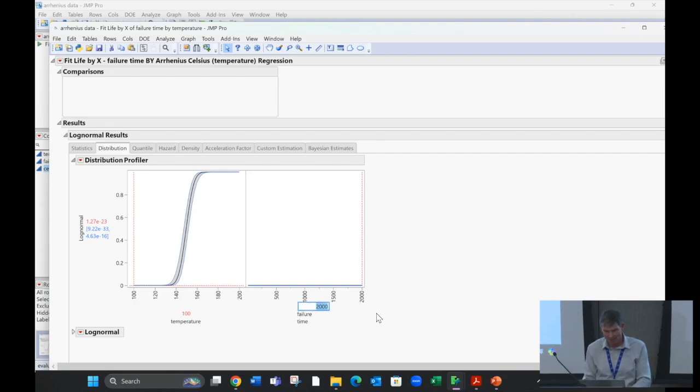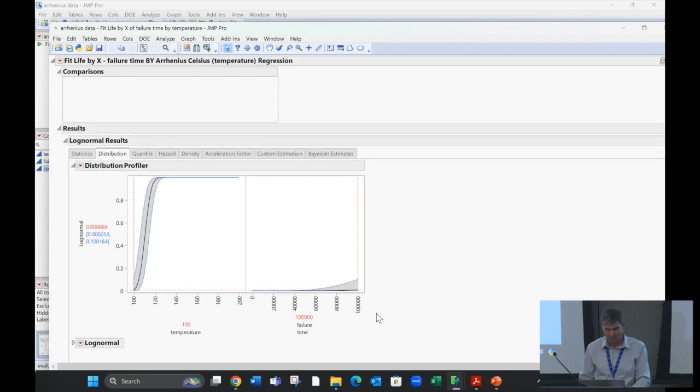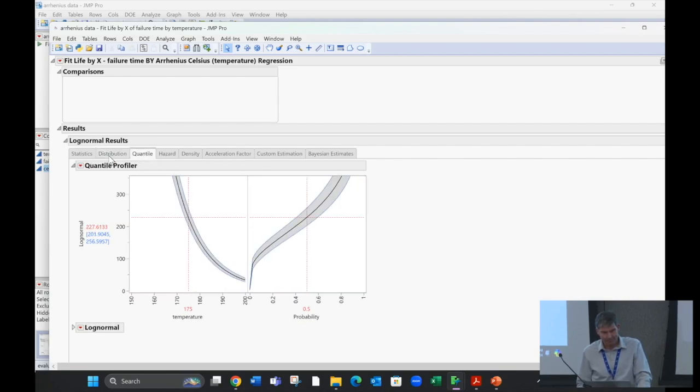And then maybe at 100,000 hours, I've got a probability of failure. So I've got almost a 1% chance of failing at 100,000 hours. Who has 100,000 hours to wait around for this to fail? And you only have a 1% chance that it will anyway, right? So the only way that we're able to develop these curves and come up with these profilers is through accelerated life testing. Pretty neat, right?